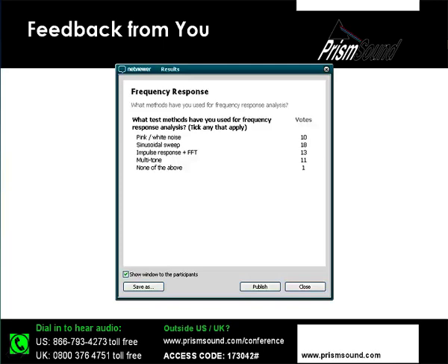I would say about the pink and the white noise method that unless you're combining that with an impulse response, you won't get a terribly clean looking frequency response. There will be variations from one data point to another that reflect the spectrum of the noise rather than variations in the frequency response of the device you're testing. So noise generally is not terribly satisfactory for measuring frequency response. You have to do a lot of averaging in your real-time analyzer or your FFT analyzer in order to get close to a clean looking result, and even then it's not that clean.